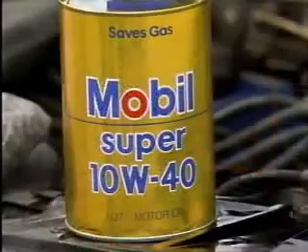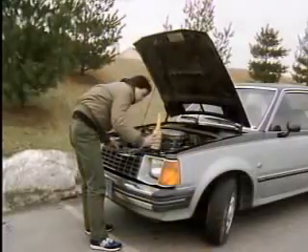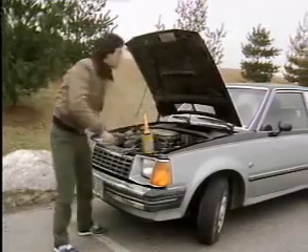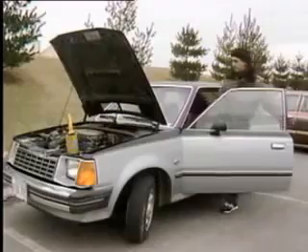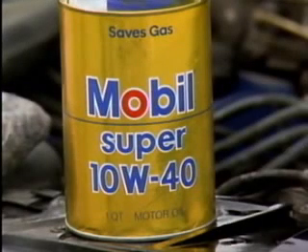In high temperatures, a thicker, high-viscosity oil is usually needed. The oil has to be thick enough, that is, have a high enough viscosity to maintain a film over the moving parts it must protect. Many oils, of course, have to be able to lubricate in both low and high temperatures. For that reason, many oils today are multi-weight. They combine the properties of a lower viscosity oil for low temperatures with those of a higher viscosity oil for high temperatures. A common example is 10W40 oil.